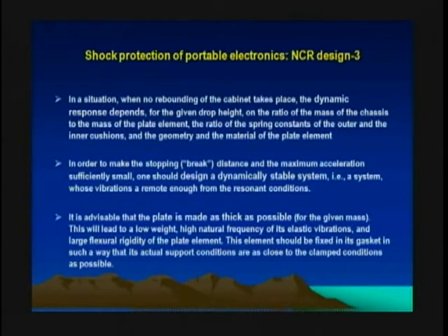It is advisable that the plate is made as thick as possible for the given mass. This will lead to a low weight, high natural frequency of its elastic vibrations, and large flexural rigidity of the plate element. This element should be fixed in its gasket in such a way that its actual support conditions are as close to the clamped conditions as possible.